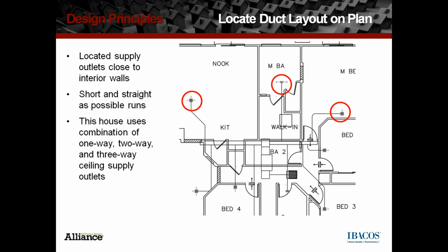Arn, one question that a lot of builders have: if a builder does this approach of locating supply registers interior into the floor plan, is there impact on trades and cost? Ideally, it would reduce the cost of ductwork because you have less ductwork, and in the effort of always keeping things as simple as possible, their installation should be faster. If this is flex duct coming off there, and this one happens to be, the less distance it has to travel, the less chance you have for it to be kinked or wrapped up or not get installed properly. So yes, there should be an impact for them. A positive impact, we would hope.